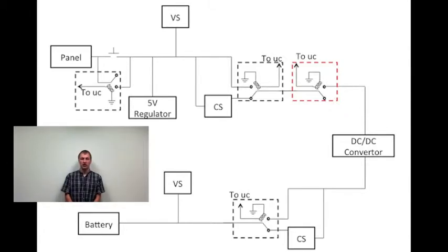After leaving the relays, the input power travels to the DC to DC converter. The DC to DC converter is able to adjust the output power by stepping down the voltage. This new output power then travels through the secondary voltage sensor, current sensor, and relays, which are implemented similarly to the primary side sensors. The values are used by the microcontroller in the perturb and observe algorithm to track the maximum power point. The power then exits our system to charge an external battery. A final sensor is placed on the battery to monitor battery temperature and maintain safe operation.